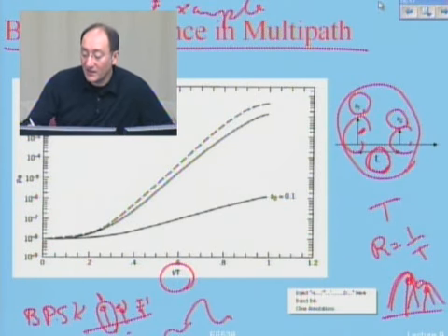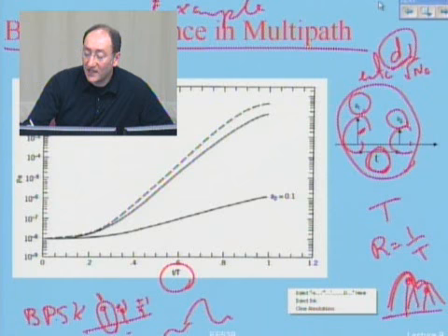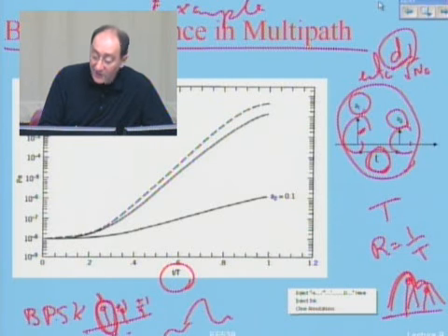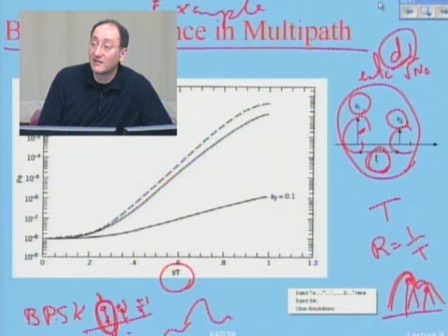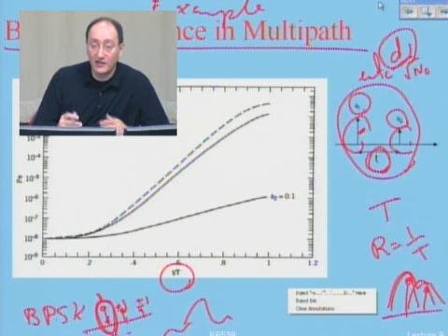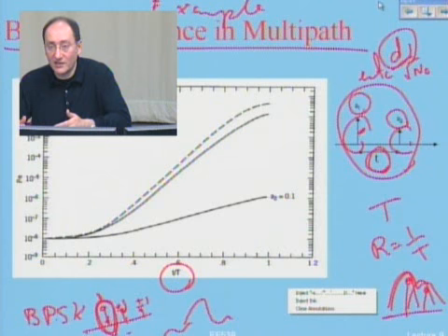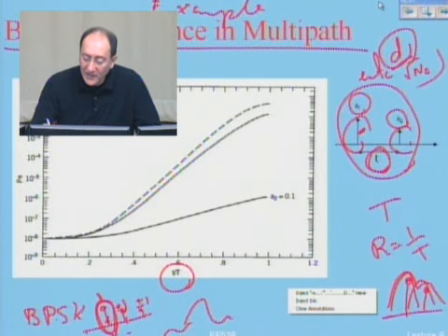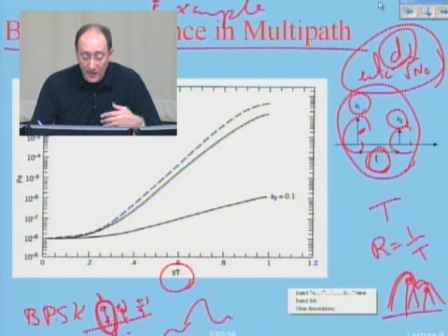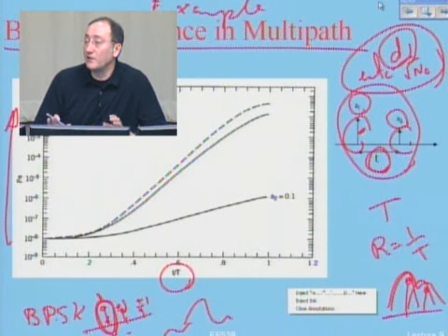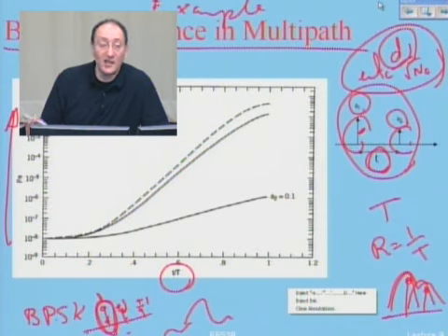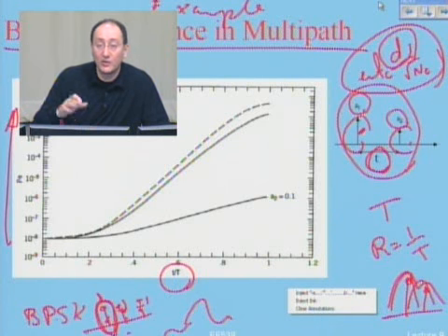Do you remember that D over square root of N0 in the ERF complement? This D, if I have one channel, is this thing. If I have intersymbol interference, it could be this thing plus this, or this thing minus this, because intersymbol interference may add to the signal or subtract from it. So based on that, I can calculate from the ERF complement function the probability of error, and this is that probability of error here, for different possibilities of neighboring bits. The neighboring bits could be the same as mine or different from mine.